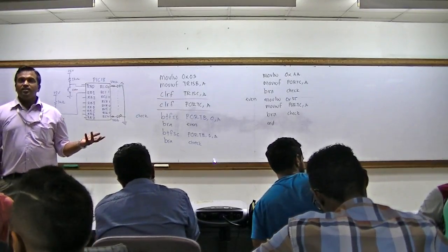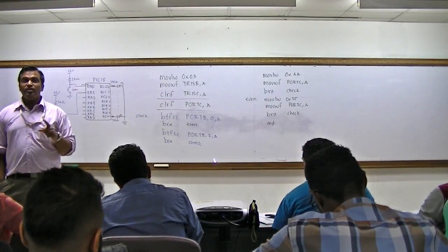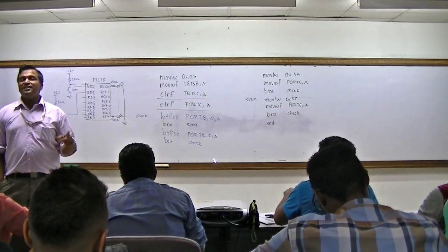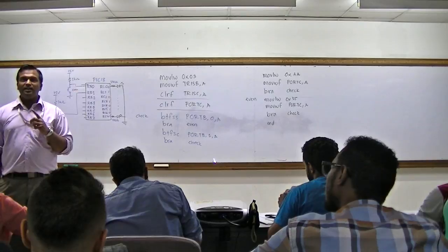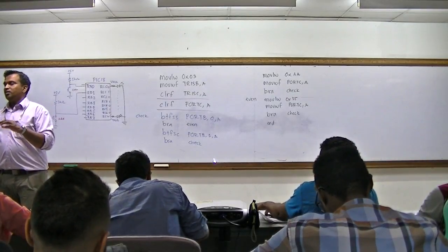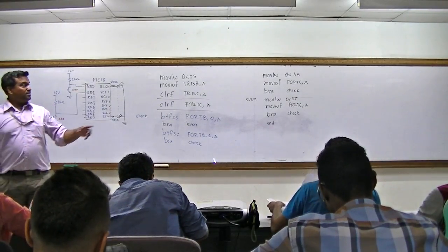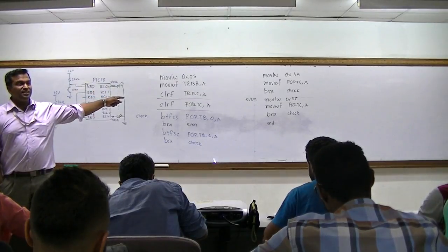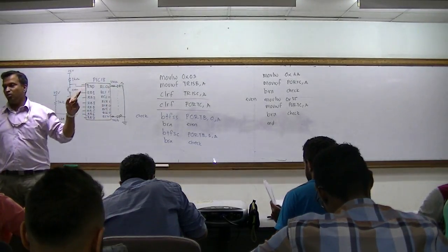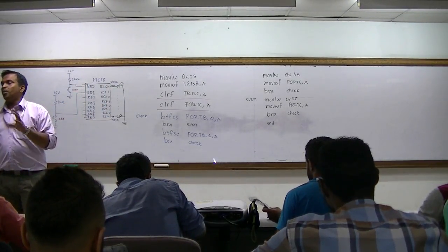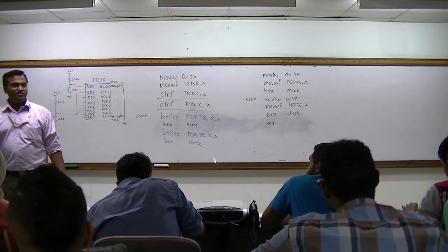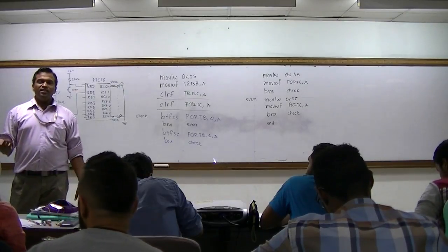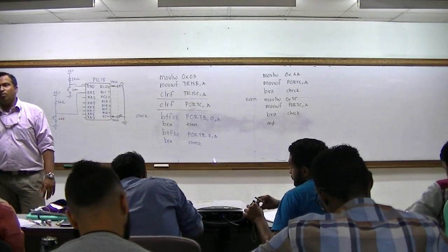Take note, whenever you configure the TRIS, it doesn't affect the port register at all. It just affects whether the port becomes input or output. When you clear TRISC, it doesn't mean that port C becomes 0. It only means that port C becomes output, that's all. So don't get confused between TRIS C and also PORTC. After that, you can just treat the port as a normal file register.